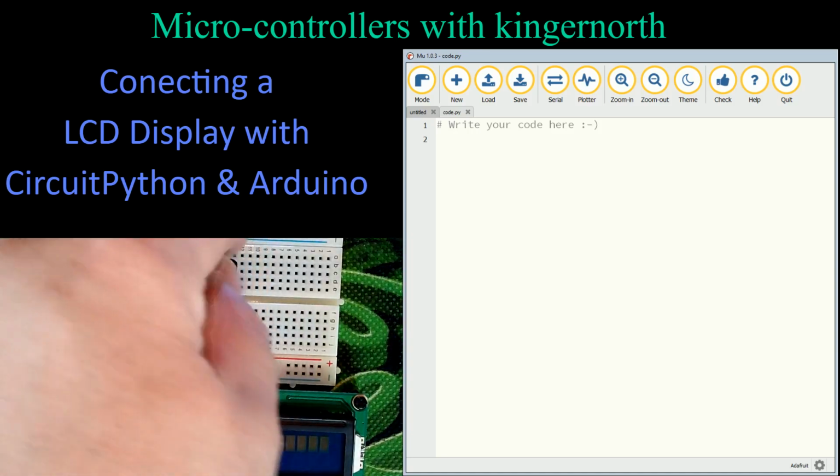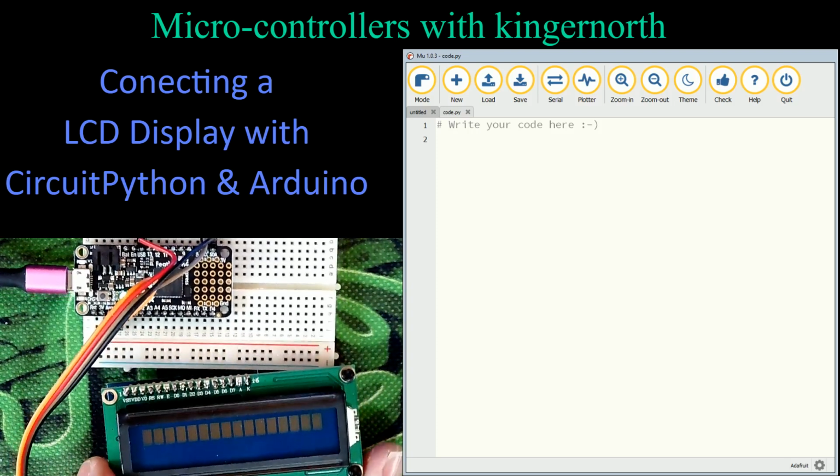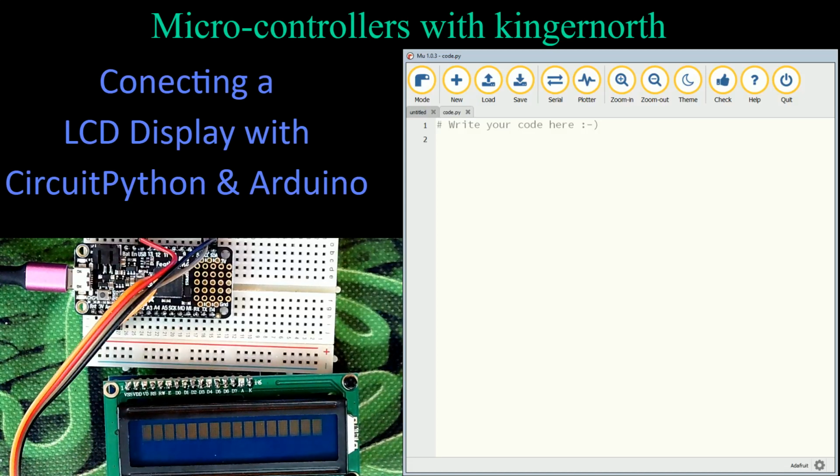And then I have on here, there are actually 2 pins marked SDA, SCL. And they just connect to the corresponding pins on the screen. So it makes it pretty simple. 4 wires, a lot simpler than that basic setup. So let's get started with this. I have my coding page up here. And what we're going to do is work through this, and we're going to write some basic code. So I'm going to start out with my comment up here at the top like I normally would. So this is an LCD test.